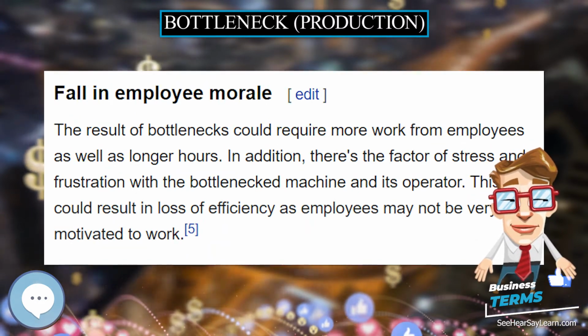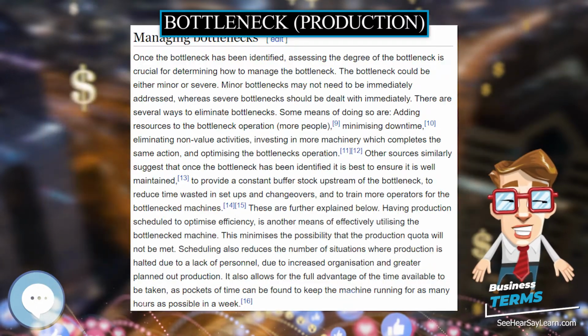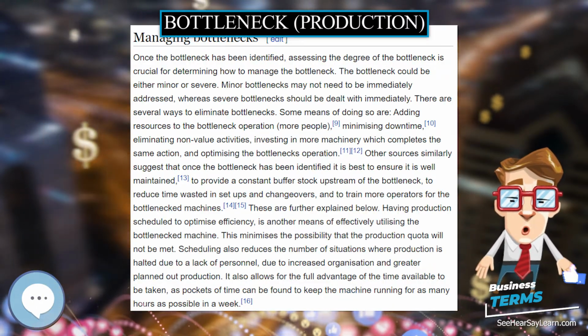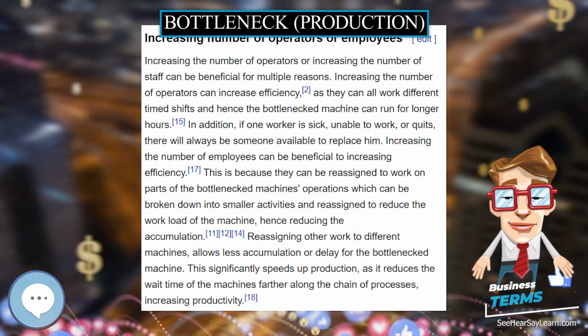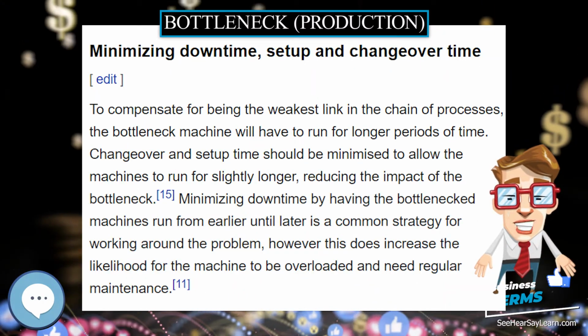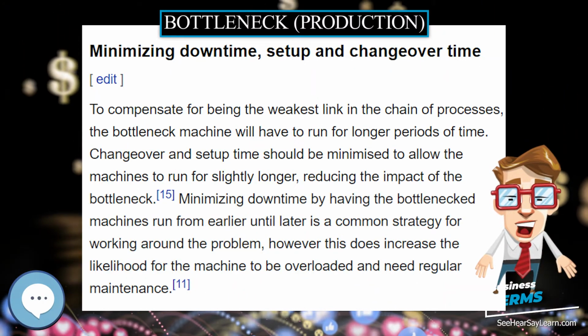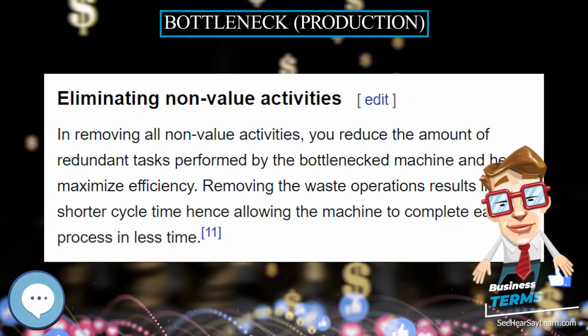Wait times. In the case where several production units are already running at full capacity, tracking the downtime of machines will allow you to identify which machine is being bottlenecked. Usually the machine prior to the machine with the highest wait or downtime in the chain of processes is a bottleneck. The result of this is a machine being underutilized.